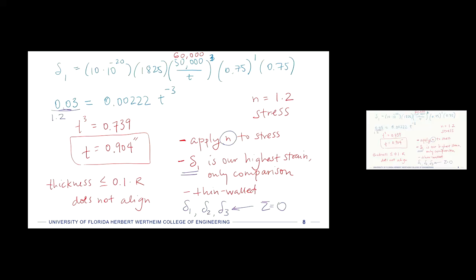However, we talked a little bit about how we assume that there's no volumetric strain for creep, but if creep is the mechanism of creating microvoids, which then coalesce into macrovoids, then the change in volume assumption sort of breaks down, right?